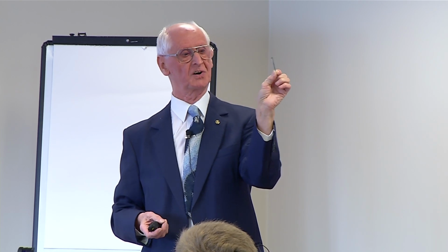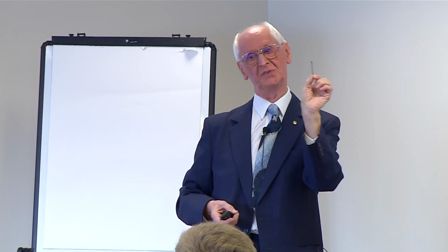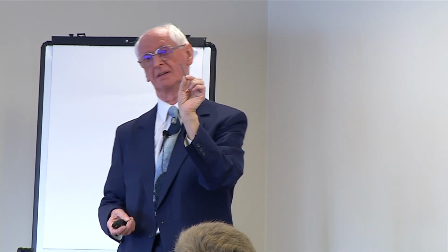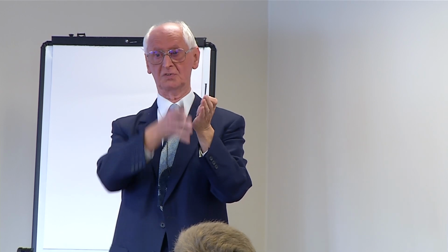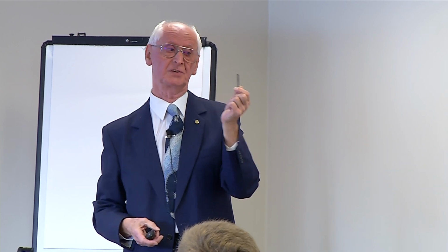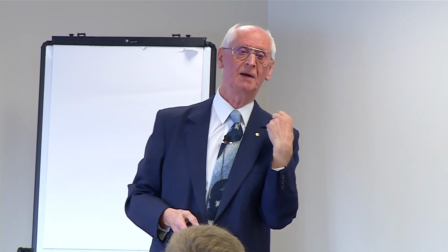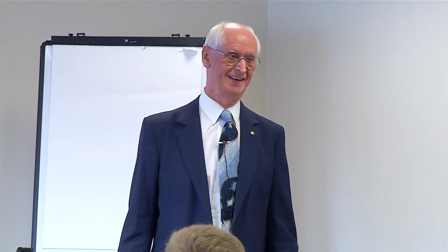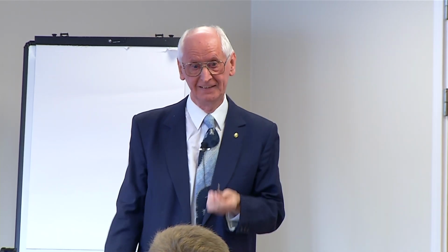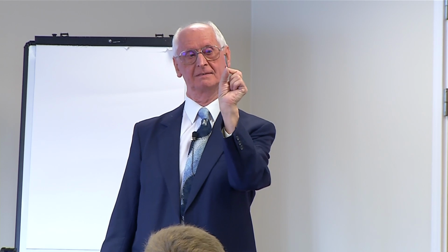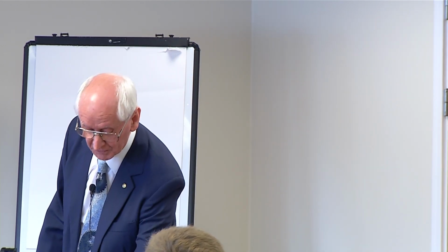You wouldn't think that's a structural fixing, but it is. These floorboards, nailed to the joists, provided a horizontal girder, basically, which was providing lateral restraint to the wall. When he took all the floorboards up, guess what happened? The wall started moving outwards. So all because of the little structural fixings which he removed when he took the floorboards up.